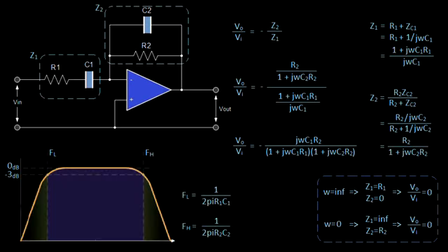So from this, we can essentially deduce that for very high frequencies and very low frequencies, all content in that range is being filtered out, which we would expect, as that's characteristic of a bandpass filter. So plugging the equations for Z1 and Z2 into the transfer function, we find this expression, and this expression will generate a plot that looks something like this.